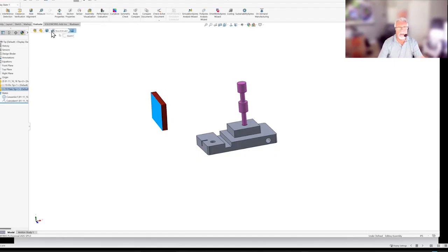But if you hit the part icon here, and actually let's use our D key. Let's pick our part, hit the D key, and now I'm going to hit it here. And now I can move my part, adjust it, get it close to where I want it. It helps quite a bit to be able to do that. And then get in there.